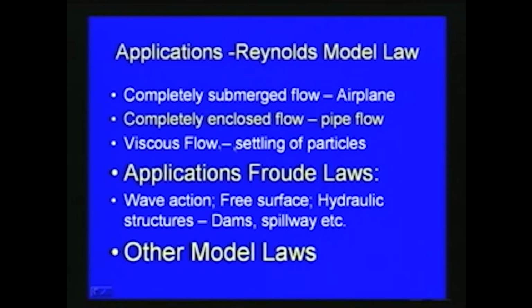And then the second one is completely enclosed flow. For enclosed flow like pipe flow, Reynolds number is more important, so we will be using the Reynolds model law. And then the third case is viscous flow, like settling of particles, like reservoir sedimentation or dust settling. In all these cases the Reynolds model law will be important, and we can utilize it.